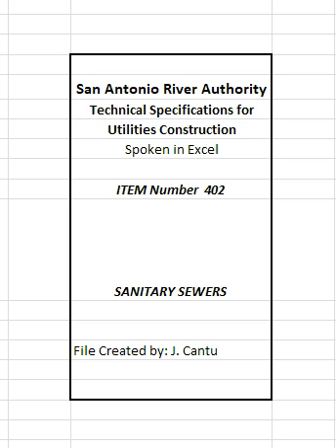B. Where a sanitary sewer crosses a water line and the sewer is constructed of cast iron, ductile iron, or PVC with a minimum pressure rating of 150 psi, an absolute minimum distance of 6 inches between outside diameters shall be maintained. In addition, the sewer shall be located below the water line where possible, and one length of the sewer pipe must be centered on the water line.